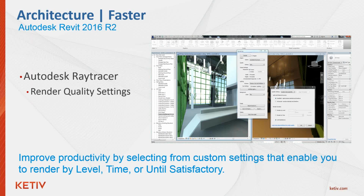All right, so render quality settings in Revit 2016 R2 is an enhancement to the Autodesk Ray Tracer, which you're probably familiar with, and it enables users to set custom quality settings for your renderings. So what you can do now is select from custom settings that enable you to render by level, by time, or until satisfactory. With the improved render progress dialog box, you can now see detailed progress information about your rendering before the render is actually complete. The benefit is you can use the quality customization options to achieve any targeted rendering result, which is pretty cool.